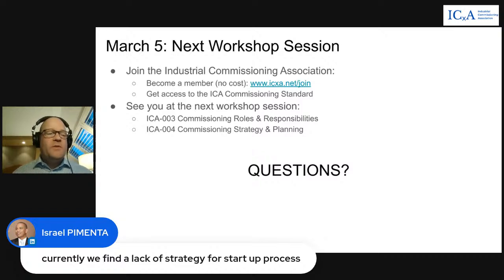Your startup sequence defines everything earlier in the project and the sequences that are needed to align with commissioning and startup. If you're not starting with your startup sequence and your energization sequence, then you're heading for chaos, guaranteed. You need to plan that startup sequence and plan that strategy before you even award any contracts on your project.